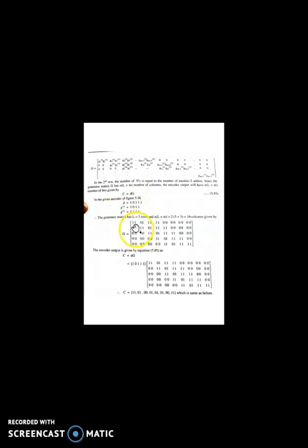Now how is the matrix written? Since it has L equal to 5 rows and N into (L plus M), which is 16 columns. You observe only two generator sequences are there. They are written two at a time: G1 G1 together, G2 G2 together, G3 G3 together, G4 G4 together. So G1 of 1 is 1, G2 of 1 is 1. So column-wise you see 1 1, 0 1, 0 1, 1 1, then 1 1. The remaining positions are filled with zeros to complete the columns.